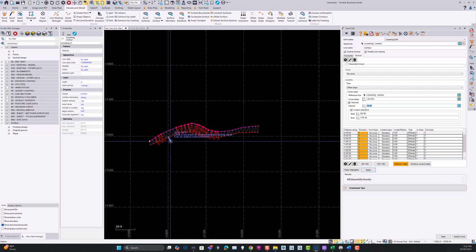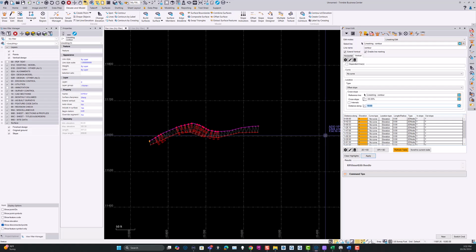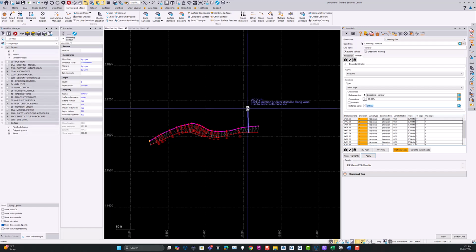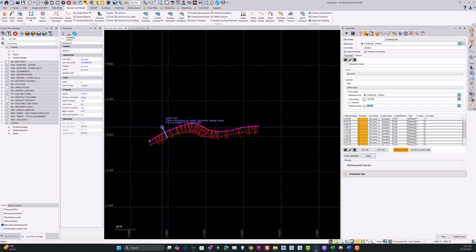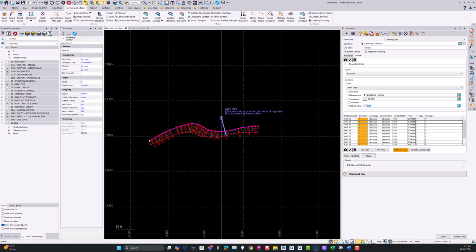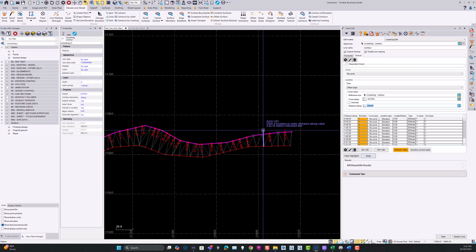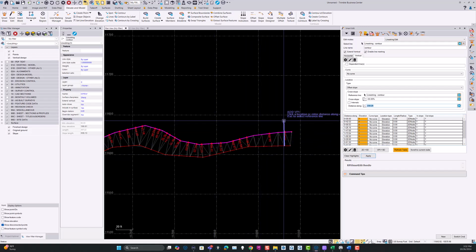and at that point it will calculate you the 3D line along here, and then you can come back in again and turn this off, and then in here the distance along we can just now add some manual nodes in to kind of complete the side slope. So you can define the whole length of the line automatically, you can do just fractions of the line, and then you can fill in some gaps with some additional points should you decide that that's necessary. So it's a very powerful tool for calculating cross slopes from a reference line with slope values along the line.